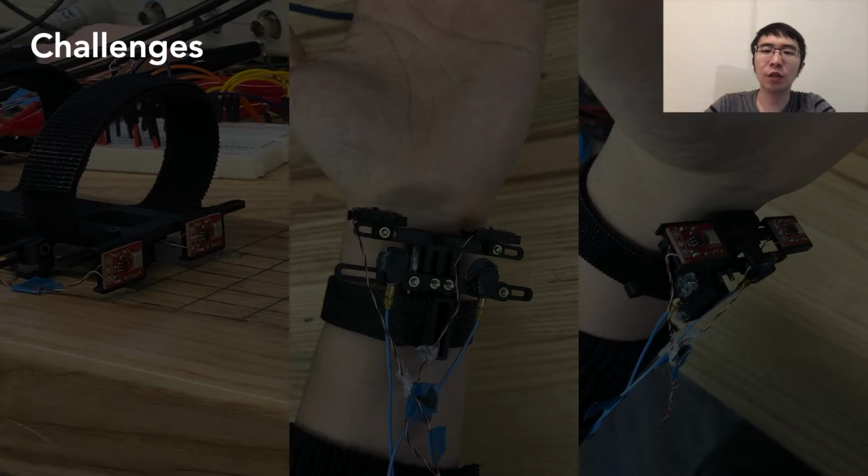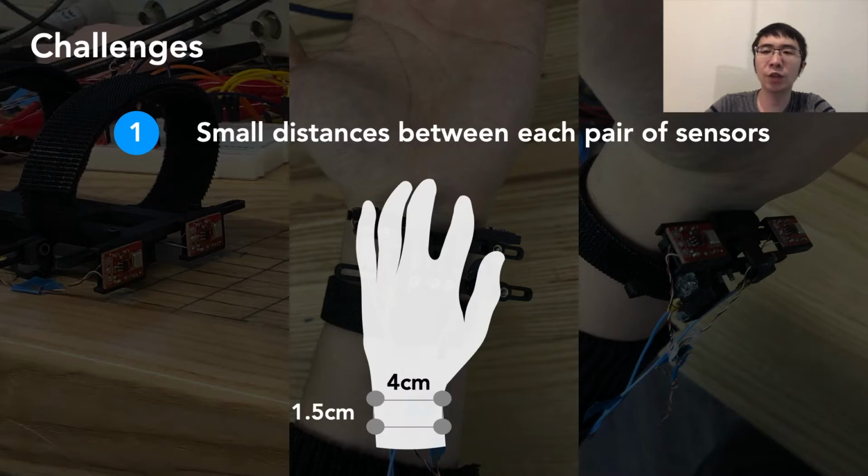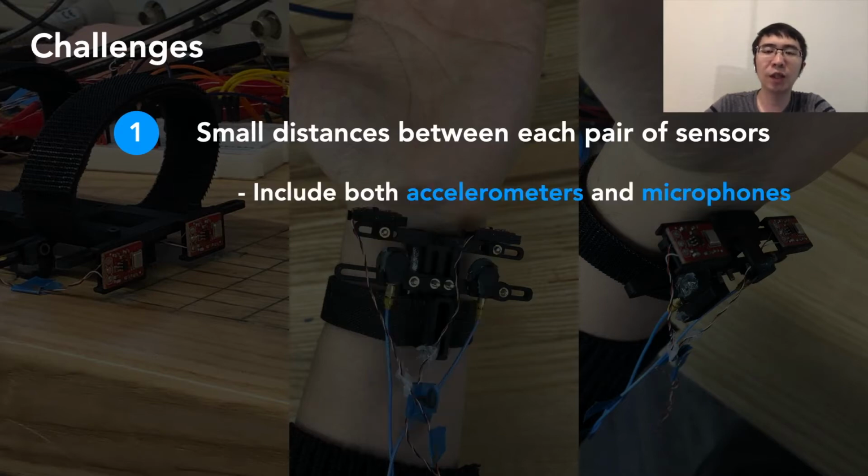The wristband form factor introduced 2 primary challenges. First is the small distances between each pair of the sensors. Due to the small form factor of the wristband, the distances between each pair of sensors are much smaller compared with existing work. For a regular wristband, it is usually like 4 cm by 1.5 cm. So this requires a more precise estimate of time difference of arrival. To mitigate this issue, we first included both accelerometers and microphones in our wristband and calculated the time differences of arrival between these 2 different types of acoustic sensors.